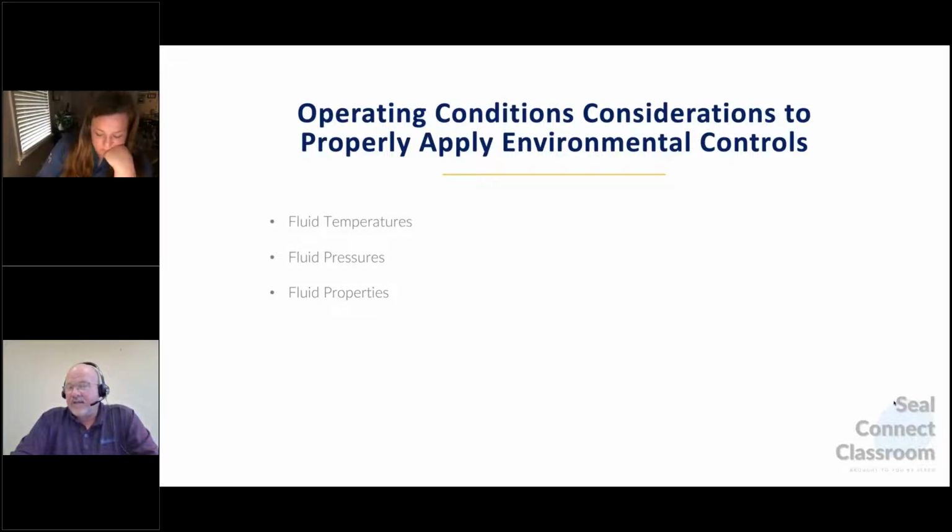So you've got to have lubrication between the two faces, so the faces don't run dry. And so boundary lubrication and having enough seal chamber pressure is really important. If not, we're going to talk about how you can create that kind of pressure to where you get proper face lubrication.